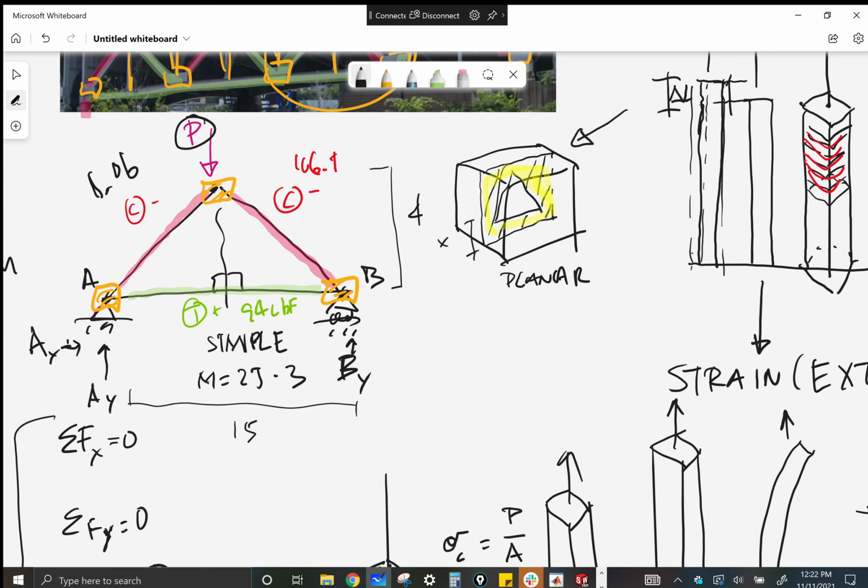That's a great question, but not in this case. If you're doing the Snell version of the project, no, because we're only designing one conceptual truss. If we were actually going to build it, then yes, we would have two, and we would have cross bracing. There'd be a bunch of other stuff we would do. This would be the first step of designing a bridge: design the shape of the truss and the materials, and then figure out how to put the two together.